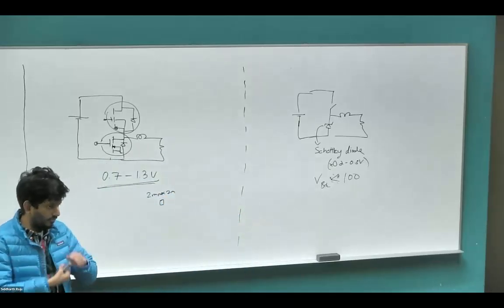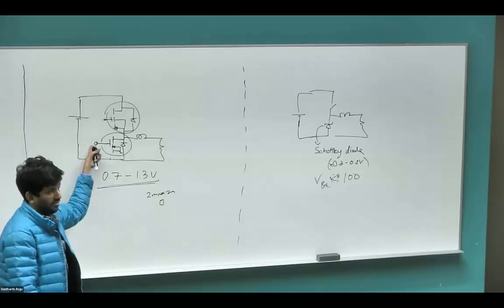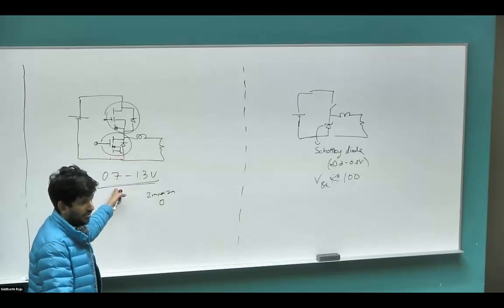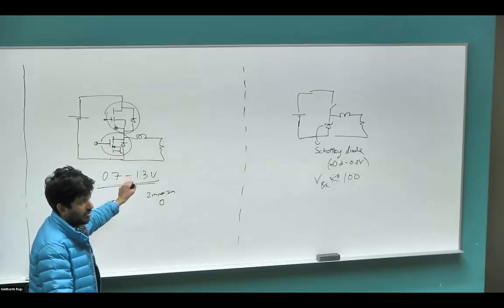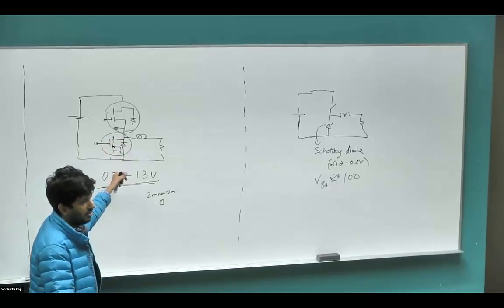So with the second switch, you're essentially just putting it there for the diode? No, not for the diode. We need to turn the switch on. Okay. Right? Because the body diode behaves exactly the same as a regular diode. It is of no use at all. So the characteristic of this body diode is exactly the same as if you have an external diode.